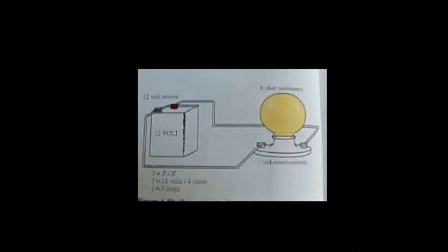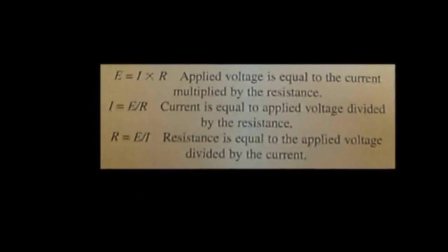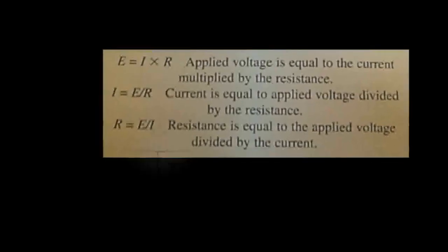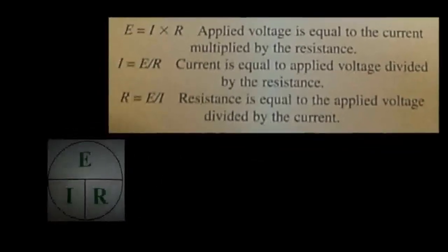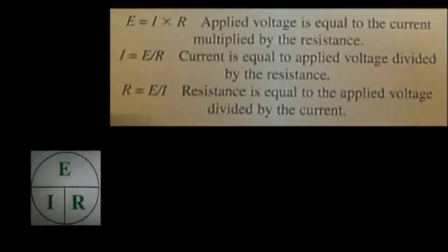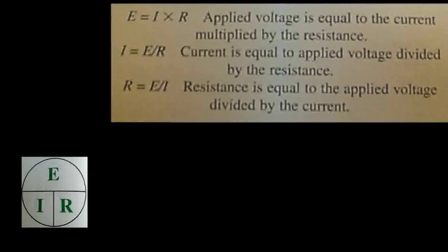As shown above in the figure, if a circuit is built correctly, it will have a perfect electrical balance between current, voltage, and resistance. This balance is known as Ohm's law. See the figure below, page 1-6. Using Ohm's law, if you know the value of any two, the third value can be found. The following symbols are utilized in expressing Ohm's law: E for voltage, I for current, and R for resistance. I recommend that you use a calculator to figure out values in Ohm's law.